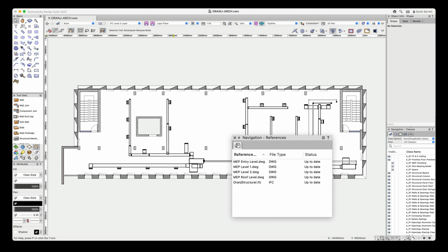I've already talked about file organization that is optimized for IFC export, but something that also needs to be considered when creating DWGs is Vectorworks classes. It doesn't matter what standard you use, as long as you stick to it. It's important for your objects to be classed logically and consistently, because it produces DWGs that are much easier for your consultants to manage.